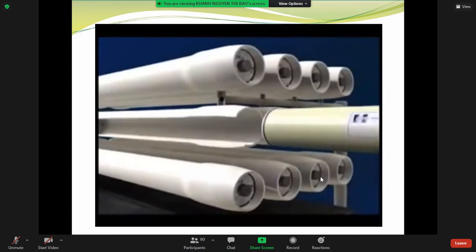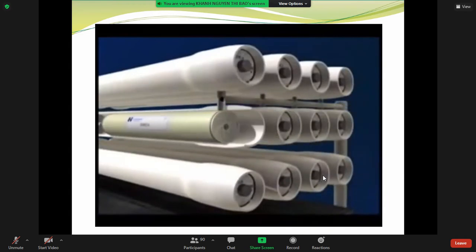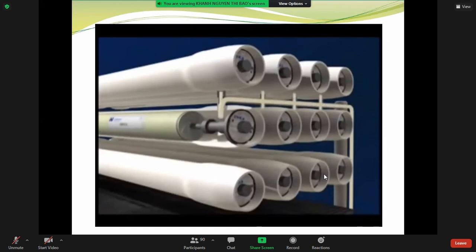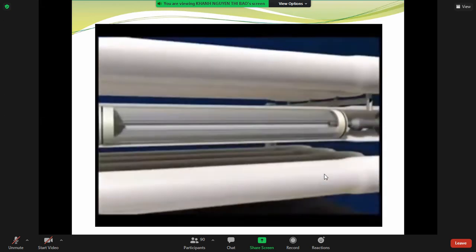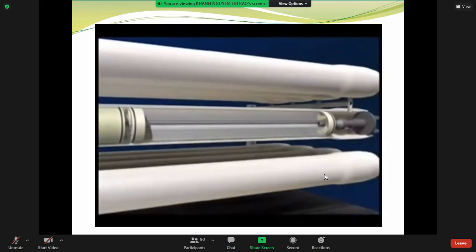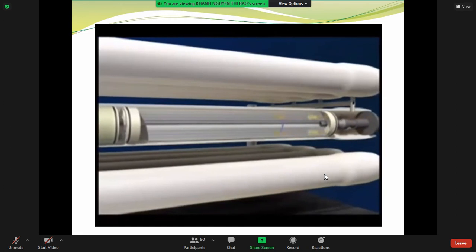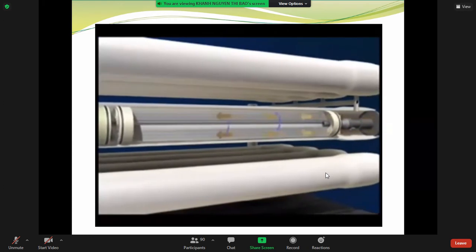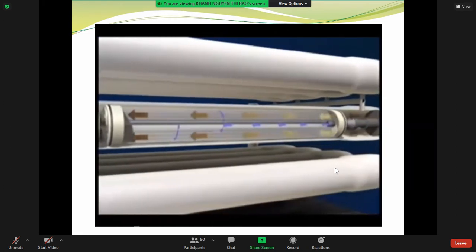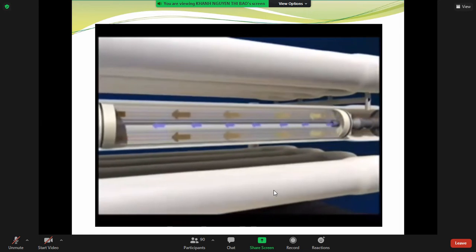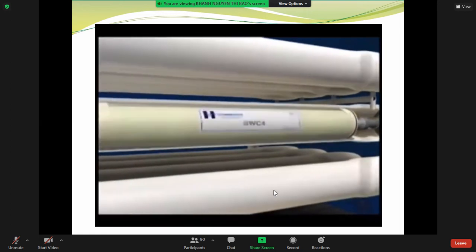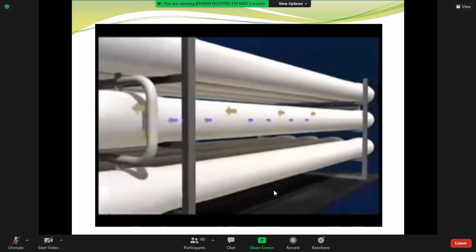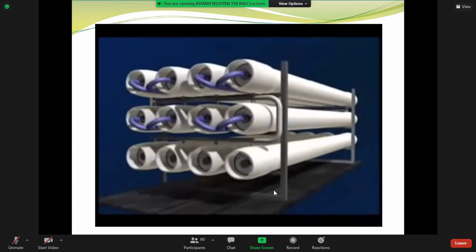Hydronautics spiral wound elements can then be loaded into pressure vessels and interconnected with additional elements to complete any number of design specifications. Once the end adapter is connected to the last element and the pressure vessel is sealed, feed water can be introduced and then treated. The feed water that does not permeate through the membrane becomes enriched in salts as it travels through the feed channel spacer due to permeate water being removed. Typically 8 to 10% of the water is removed in one 40-inch long membrane element.